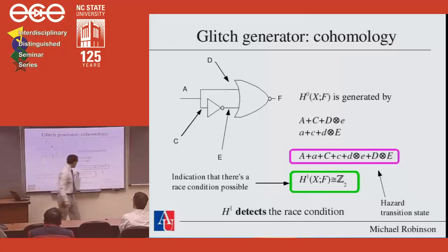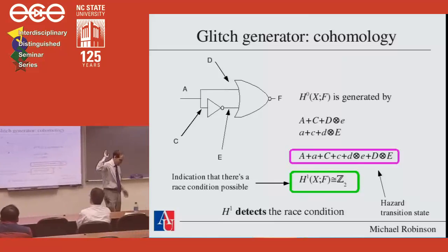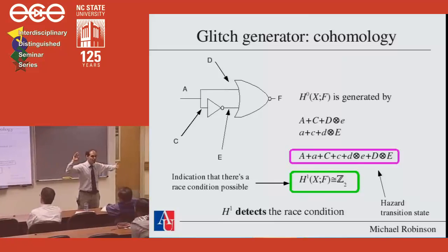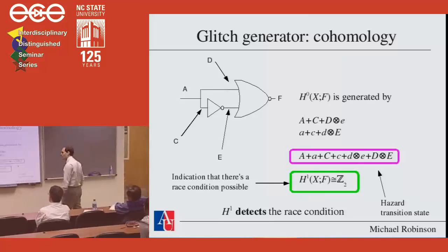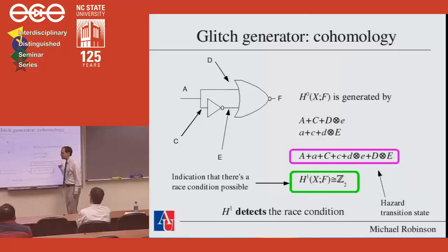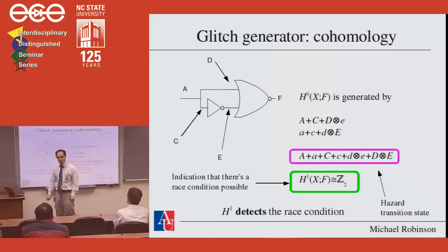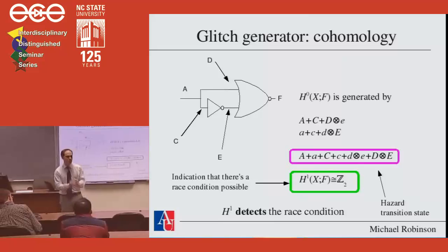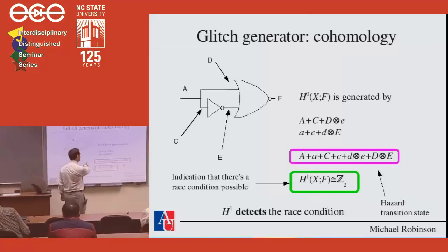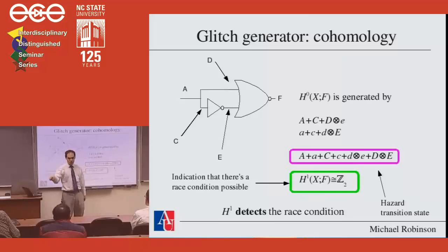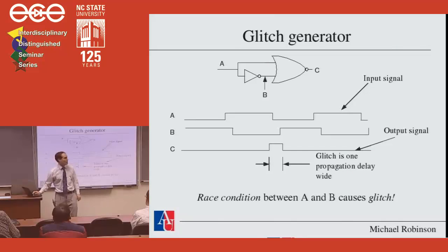This one here, notice, is saying that I have a logic 1 and a logic 0 superposed on the input, and the output has a logic 0 and 1 superposed on the output. I am in transition. It is possible to make this circuit do something interesting. Interestingly enough, we don't know exactly what it is doing. It could be going from 0 to 1 or 1 to 0, which is saying that we've lost some information here. I don't know that it is the falling edge of the input that's the problem. But I do know one of these edges is the problem.